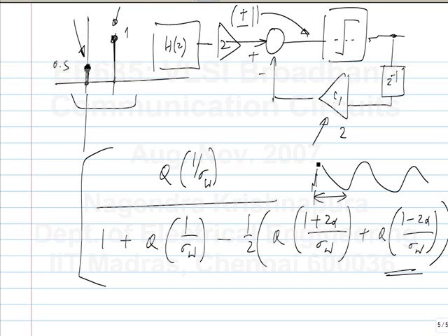Yeah, that's true. That is also why, like this truncate, after a point there is no point having more taps, because you can't really adapt it very precisely. Firstly, there is this adaptation jitter, and one potential thing you can do is you let it adapt and then stop the adaptation, right? So then the coefficients are exactly constant. But even then, the precision to which it has adapted may not be good enough. So that's why, I said 0.01, but even much smaller taps you don't realize.